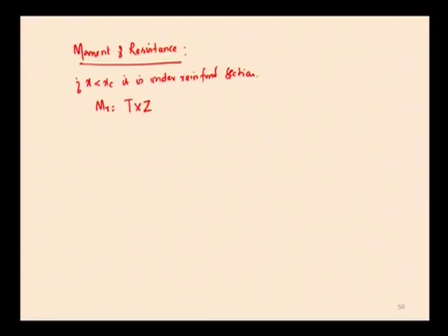This we know that, in the case of under reinforced sections, steel is stressed to its maximum permissible value first, while the concrete is stressed below the maximum permissible value. The section normally fails initially due to overstress in steel. So, the moment of resistance is T into Z, which is equal to T1 into Z1 plus T2 into Z2, where T1 is AST1 into sigma ST into the respective lever arm Z1, d minus x by 3, plus AST2 into sigma ST into d minus d dash.